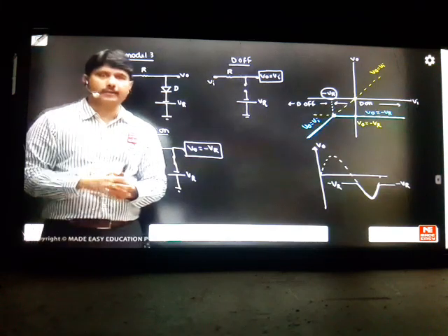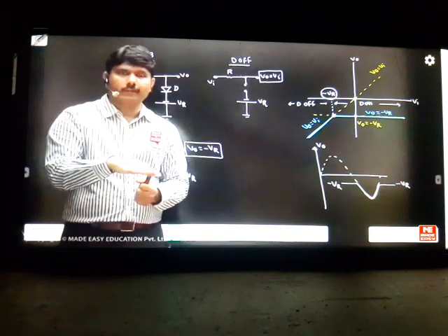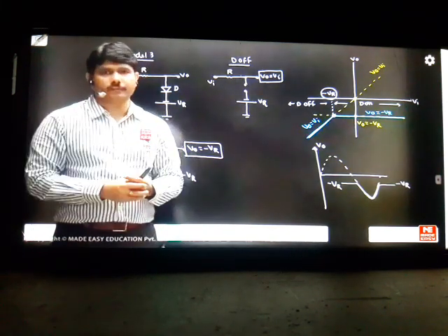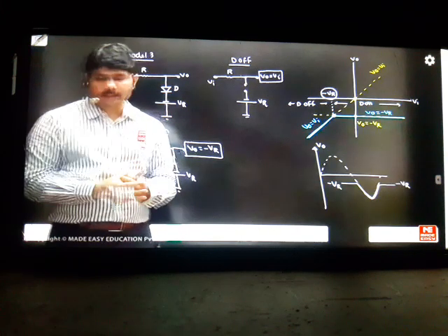At the anode side, you are dynamically changing the value. That value can be below this cathode or above this cathode you are giving. Then how can you say that the diode will always be on? You can say always on when you give a constant voltage at the anode, but these are signal conditions.